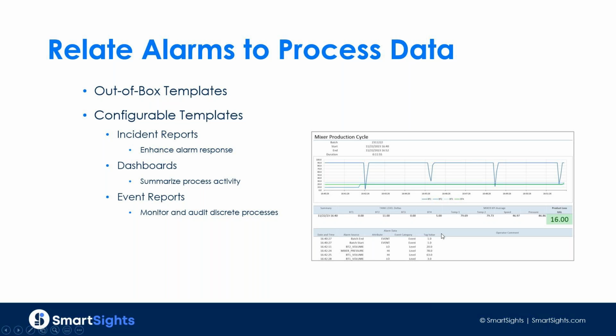And you can also design discrete event reports, right, that monitor something like a production cycle or a batch, that are exposing all the data points that are happening in that process to people, exposing the alarms that are happening in that process, and collating all this information. The process data, people's responses and comments and acknowledgments to alarms all get tracked within this discrete audit kind of a report.